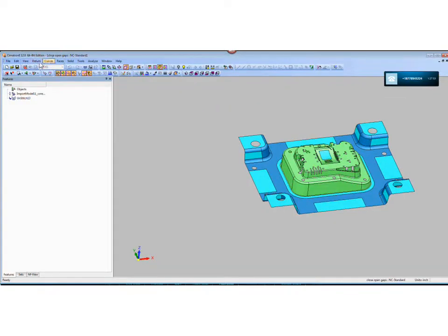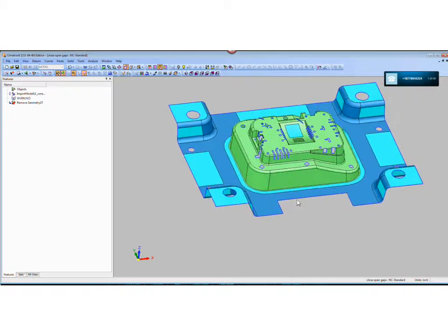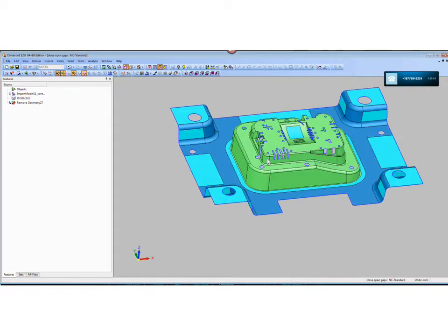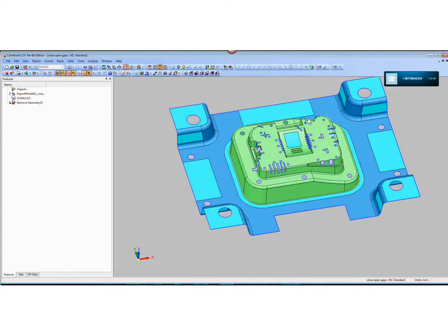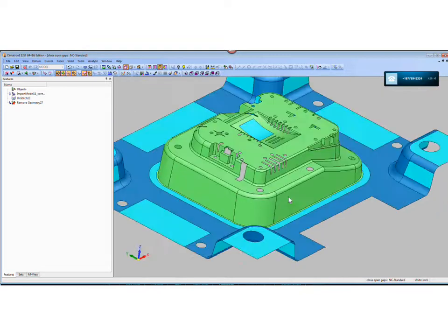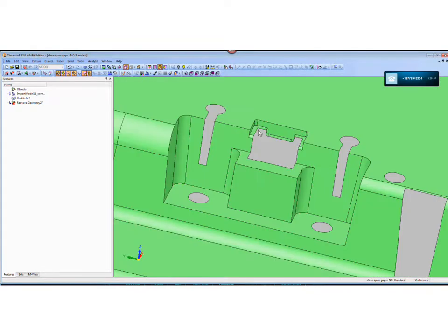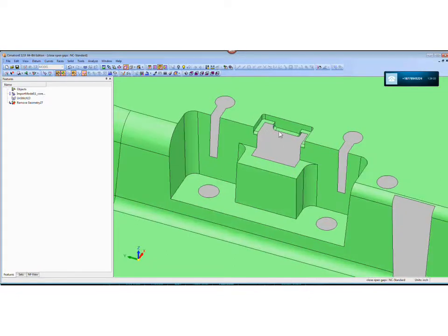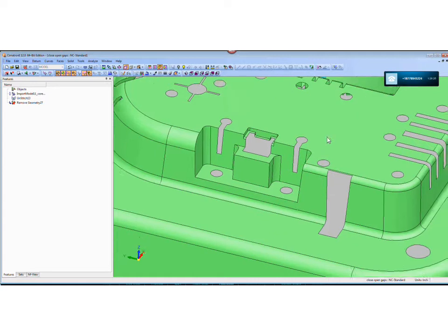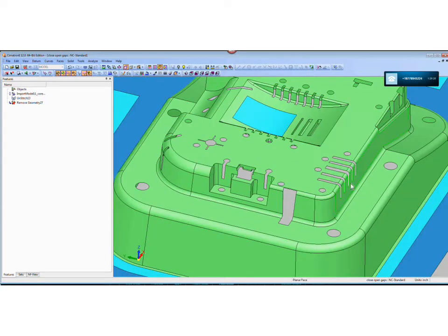And if I show you the open edges on my job, these are all open edges. In other words, this is not a closed, watertight, solid model. It's just a bunch of surfaces that are stitched together. And even so, in fact, let me just point this one out real quick. This one, if I want to put a patch on, wouldn't just be a matter of doing a chain around there and making a flat surface. There's a little bit to be done here. And if I told you that the webinar wasn't going to end until all these surfaces were patched, guys would probably start exiting quickly. But watch this.